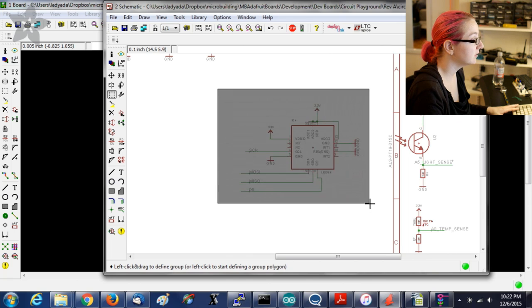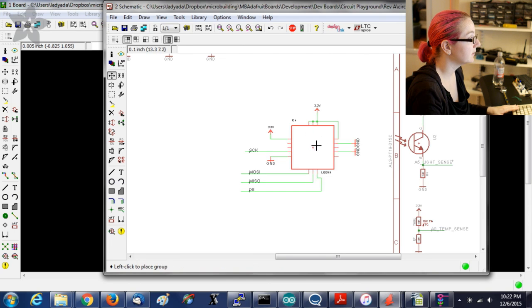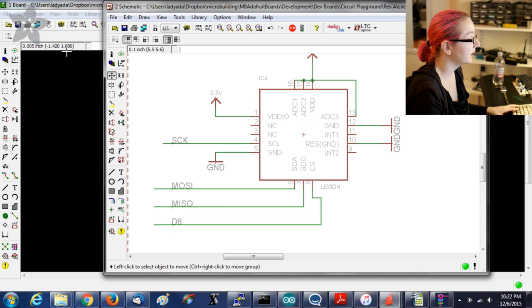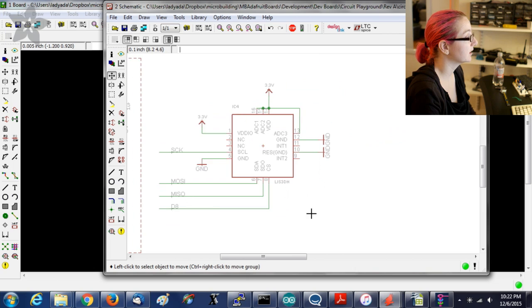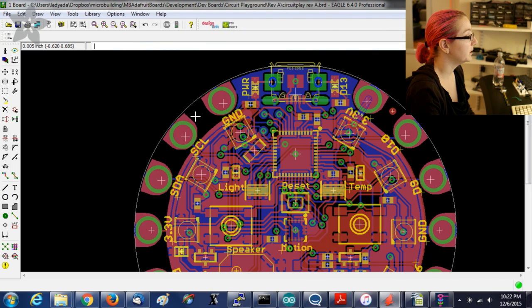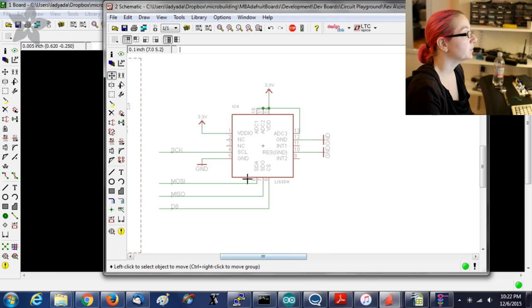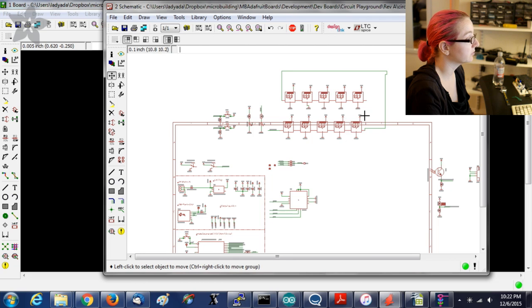So this is sensor number 1, and this is the LIS3DH. And in this case, I'm using SPI. I'm using SPI for this because the I2C pins, I'll tell you in a moment, are going to be used for other things, and I also want to keep them available. So even though I could have put this on I2C, I ended up putting it on SPI, which is fine because I have library code for that.